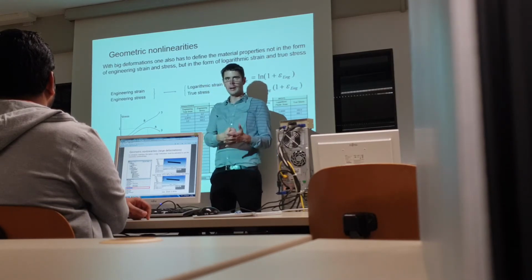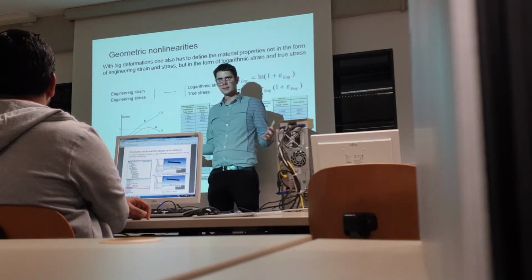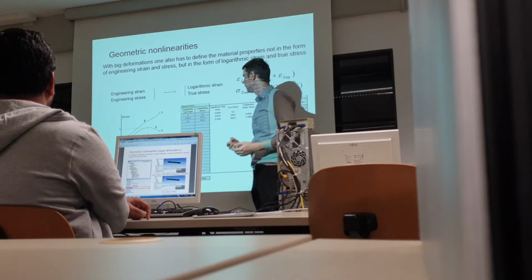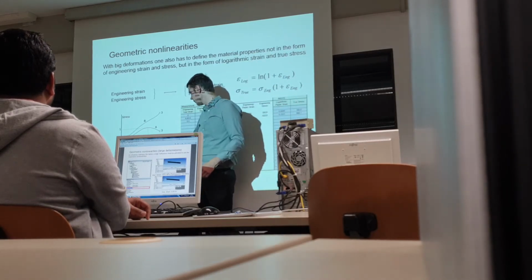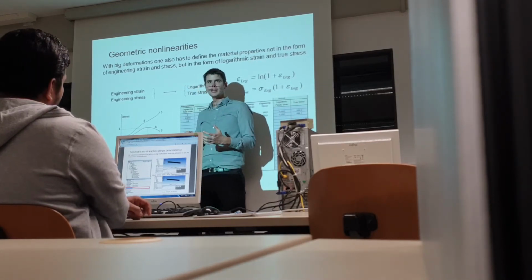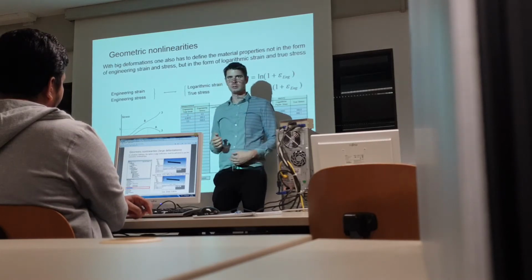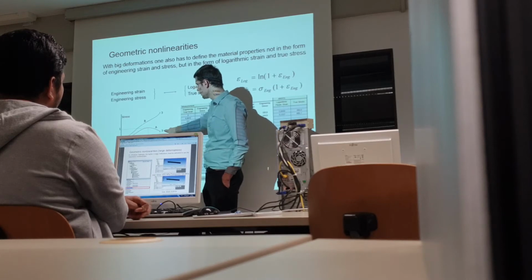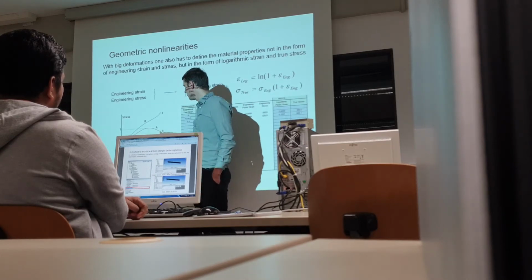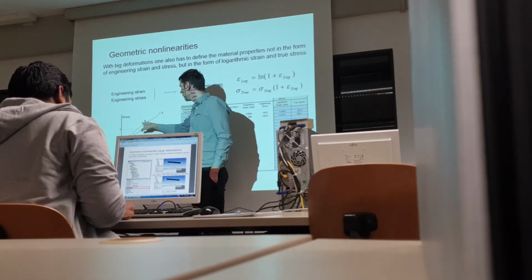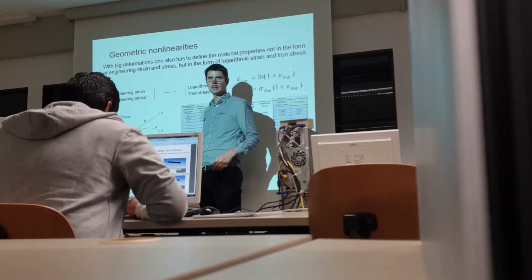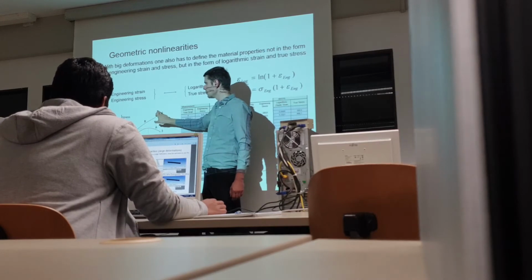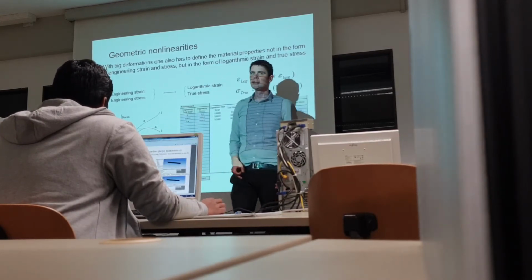But in reality, my area is always smaller, and at break my area is really small, so my stress at break is much higher than the measurement. So I have two lines: one line is the measurement, and in real it looks like this, my stress-strain diagram. So my stress at break will be much higher in real.